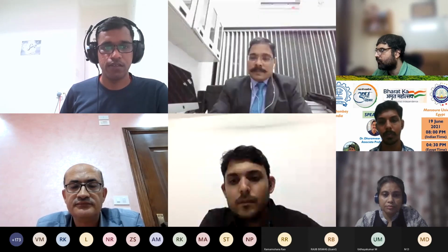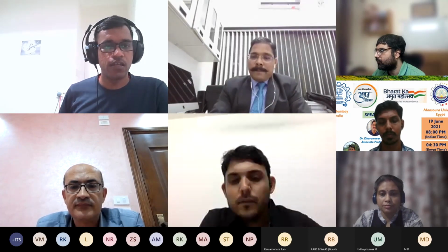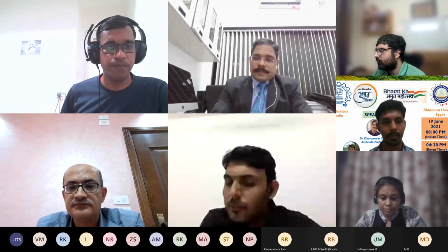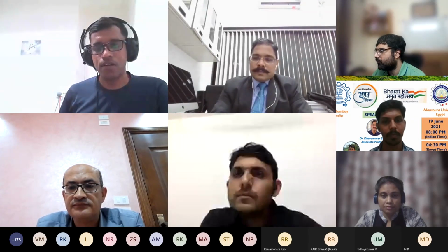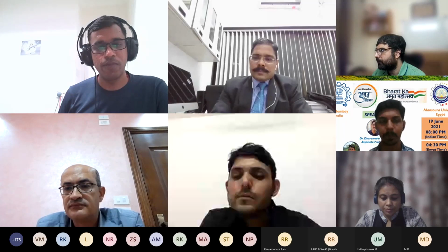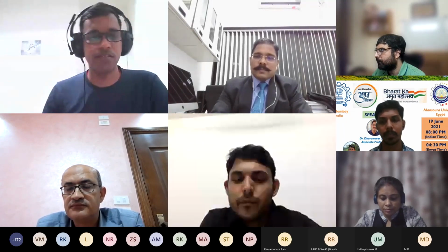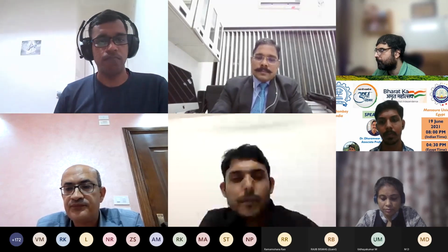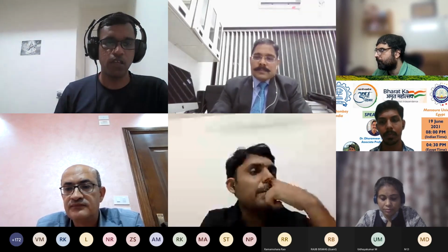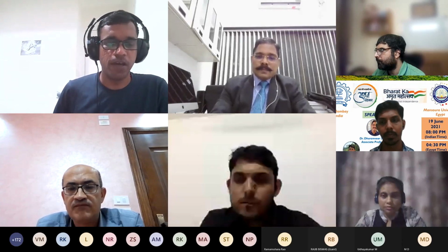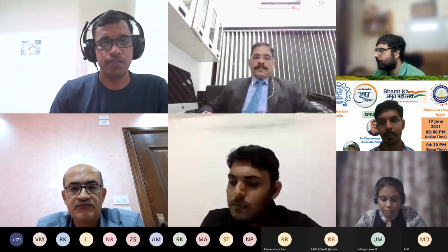Yes. Thank you, sir. And another question has come up, a very simple question: what is JNR? So JNR is nothing but the non-recoverable creep compliance. Essentially, when we do the multiple stress creep recovery test on polymer modified binder, especially, or maybe crumb rubber modified binder, you can measure this parameter from that test.